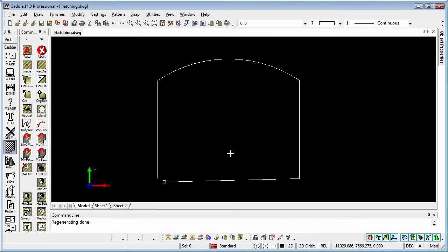And then just to recap with our other option there, endpoint, what I've done here is I've taken the polyline and just exploded it into individual lines, but notice that it now doesn't join up. Something that can be a source of endless frustration when hatching is that you can't get areas to track automatically, especially when you're dealing with somebody else's drawing, so you've had no control over the actual creation of the drawing. It might have been drawn well, it may have been drawn maybe not so well.